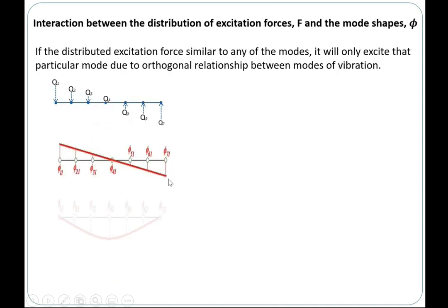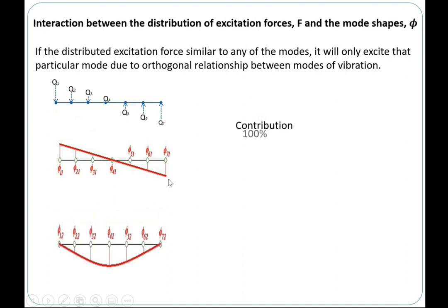All right. So another factor is the interaction between the distribution of the excitation force and the mode shapes. Basically, we look into how your force interacts with your mode shapes. In the case of these beams, let's say you have a first mode something like this, and a second mode something like this.